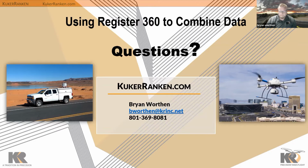So Bryan, we have a question here from one of our attendees. Does Register 360 still only use the cloud-to-cloud points within a specified distance from the single waypoint setup created after importing the LIS? Because in the older versions, you needed to create a couple of waypoints through the LIS file to incorporate better cloud-to-cloud registration points.